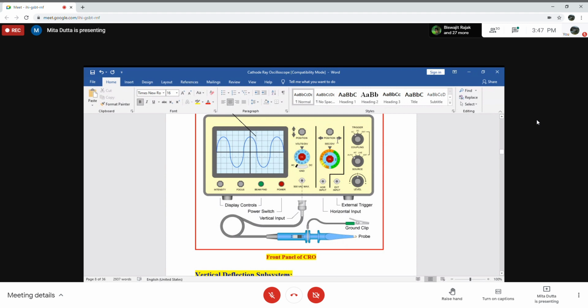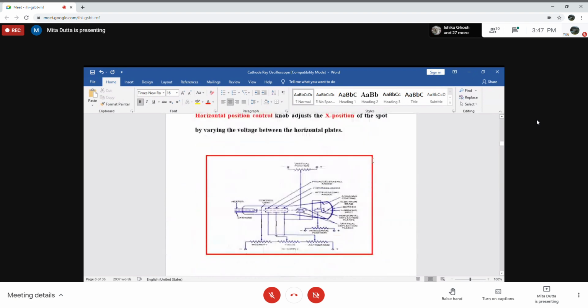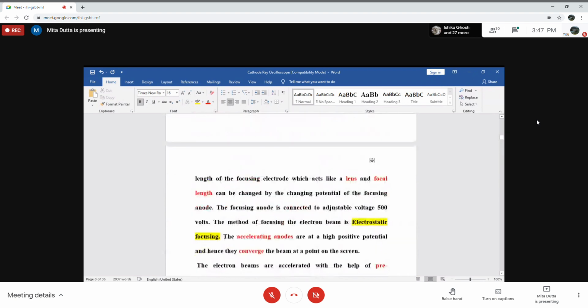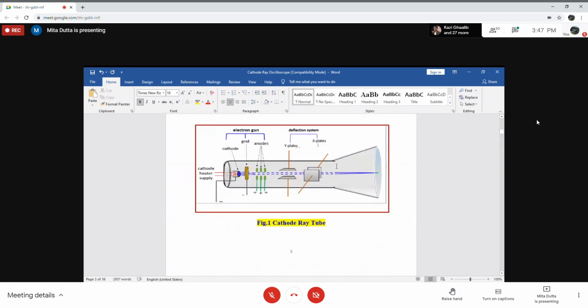And what are the functions of these knobs? I am coming to this now, and also AC, DC, external, internal. This I am coming to later on. So this will be the intensity control knob, and this knob is marked as intensity on the front panel of the oscilloscope.